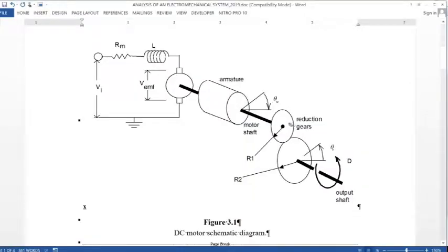So let's go back to our motor. What we can see is that there are two sides of a motor. One is when we push current through the motor with our north and south poles, it makes the motor go. But there's another side to the motor which says that if I grab a hold of the output shaft of the motor and put a disturbance torque on that motor to make that motor move, it also generates a voltage across the motor that we're going to call the back EMF.